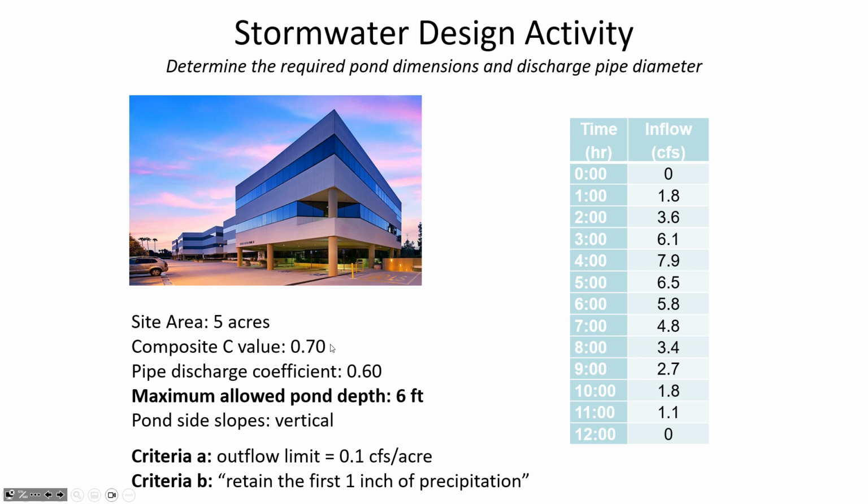And also we want to make sure that the pond doesn't get too deep, because if ponds get too deep, then a variety of troubling things can happen. Like if a pond is really deep and it's meant to be a wet pond that always has water in it, then the wind that causes the water to circulate in the pond doesn't actually penetrate down to the bottom, and it can have layers of water at the bottom of the pond that get very little oxygen.